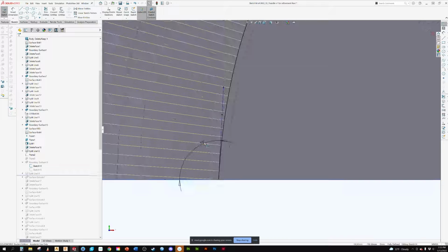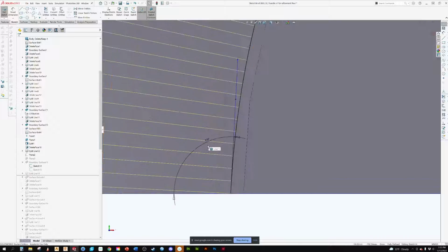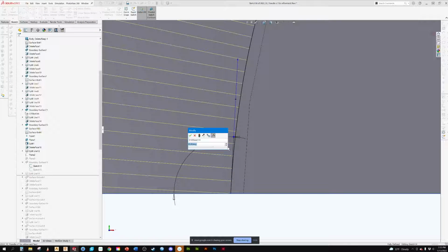But then what I did is I went in and dimensioned it. Because if you recall, and we'll get into this more, that first dot, that diamond, means tangency. The arrow means curvature. So what I can do is I can come in and say, oh, so I know that 3 degrees is what I need. So I make this and I say go 3 degrees.